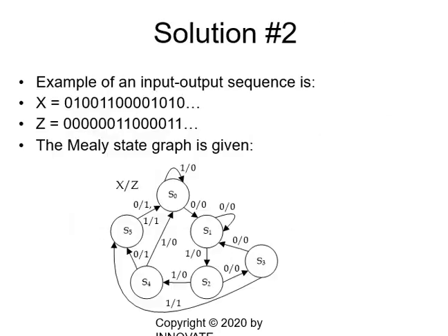To do that, again we have X, and once we detect 0 here, I have 0, 1, 0, 0, 1, 1, 0, 0. So I have 0, 1, 1, 0, and I have 1 first at the last input 0. Then I have 1 at Z again. So we have 2 outputs of Z, which are 1, 1. So 2 consecutive outputs, and after the second Z, the network will reset.